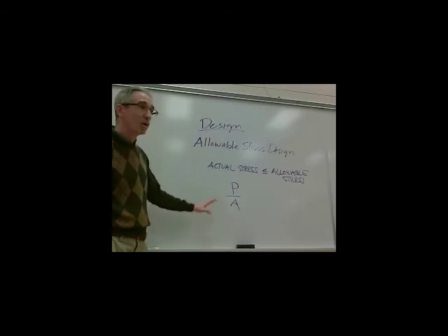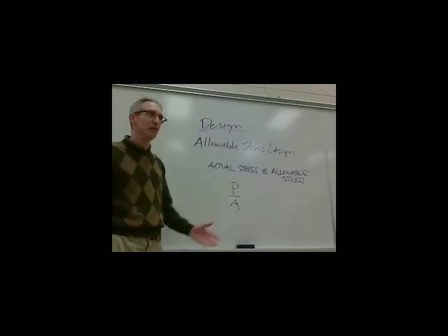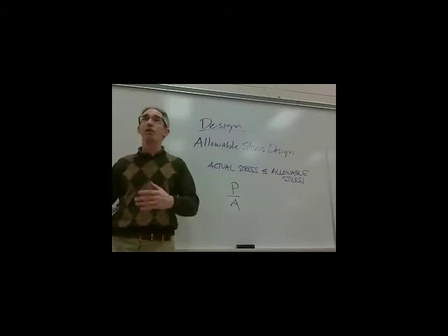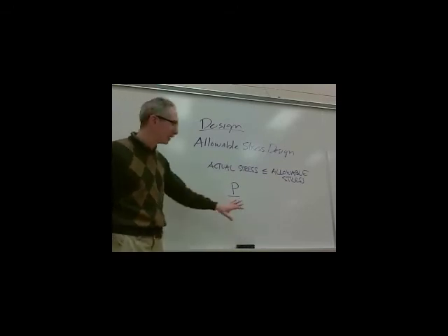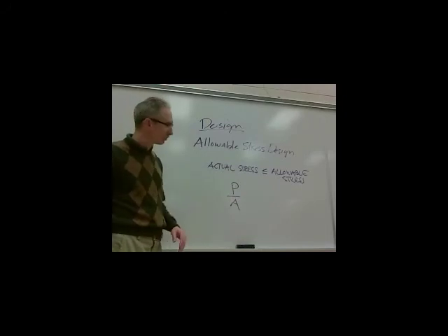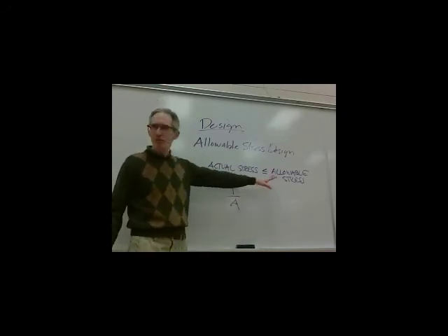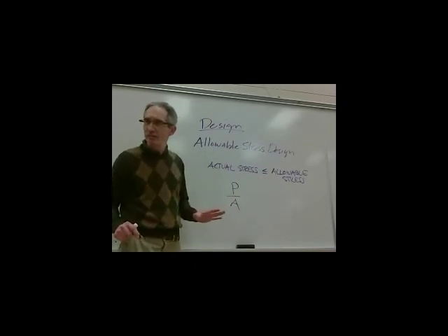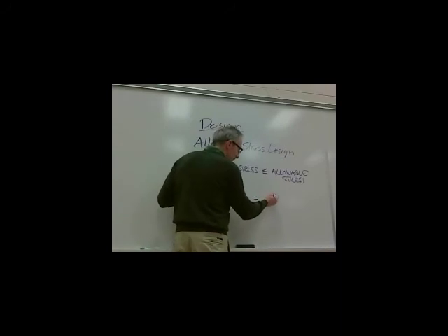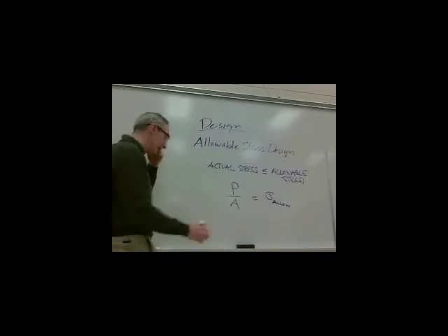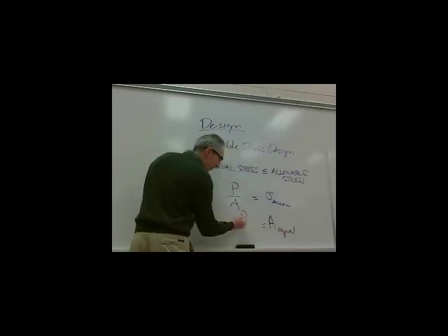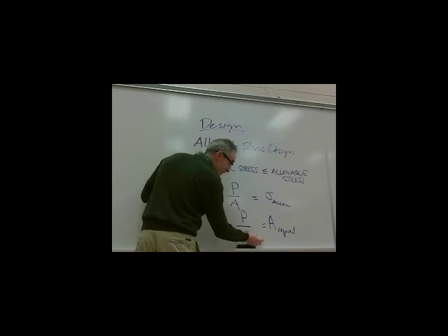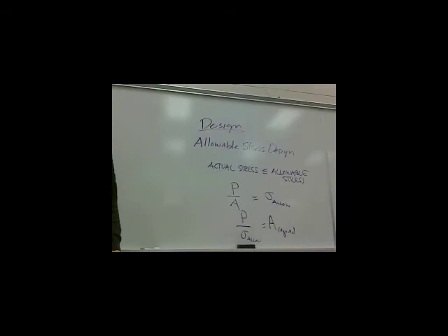Area. So, what I'm trying to tell you is, if you're really doing design, a lot of times you're designing the area or some function of area. Maybe a little bit later it'll be the moment of inertia or the section modulus. But for right now, think of area, since that's all we're dealing with. Could I rearrange this formula and maybe solve for area? Yeah, sure. Let me just call the allowable stress this: stress simple, allow. If I was going to solve for the required area, how about saying P divided by the allowable stress? So that could work, couldn't it?